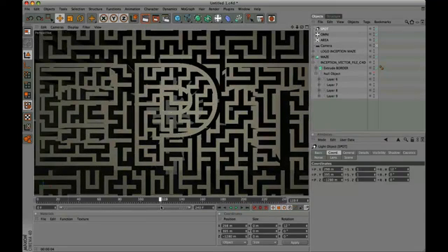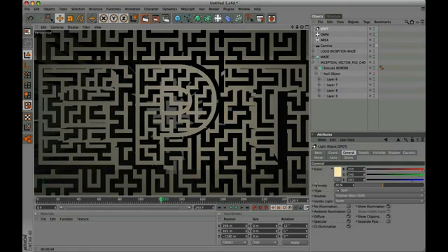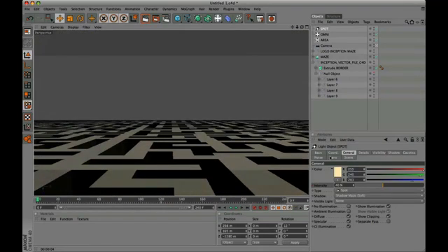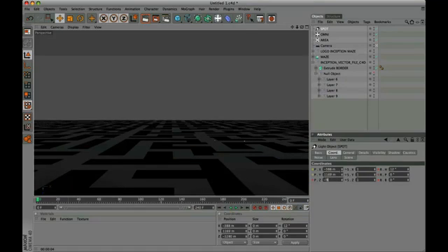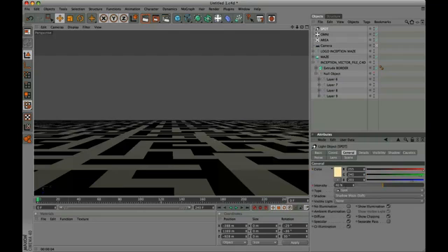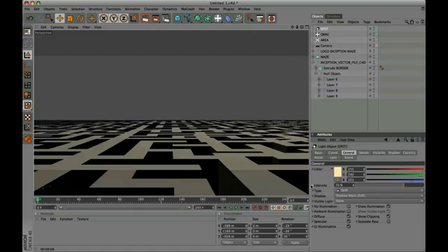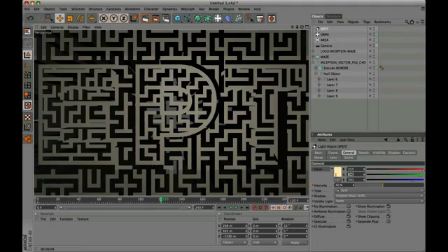Go to frame 120, activate the coordinates keyframes for position, and the intensity keyframe. Go to frame 0 and insert the values X minus 388, Y 1169, Z minus 928, rotation minus 29, minus 36, 30. Activate. We bring intensity to 70. In this case, we apply an animation to change the color. Activate a keyframe on color, return to frame 120, and activate the keyframe with white color.